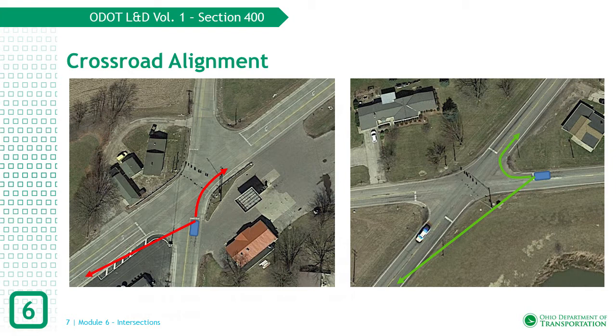The image on the right shows the acute angle on the driver's left side. This is a much better visual angle for drivers who are looking at approach vehicles to find gaps and turn right on red. For this, right turns on red may be permitted. NCHRP Report 600, Human Factors Guidelines for Road Systems, goes into detail about this angle concern.